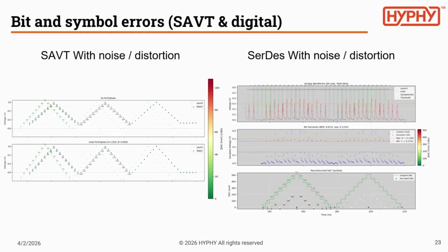But as soon as there are more transitions within a single digital pixel, so ones and zeros are alternating, then you can see here that the actual target value is not achieved, and there are more and more bit errors in the transmission. It's safe to say that here the image is not transferred. So the digital system does not transfer the image, whereas the analog system transfers the image correctly all of the time.